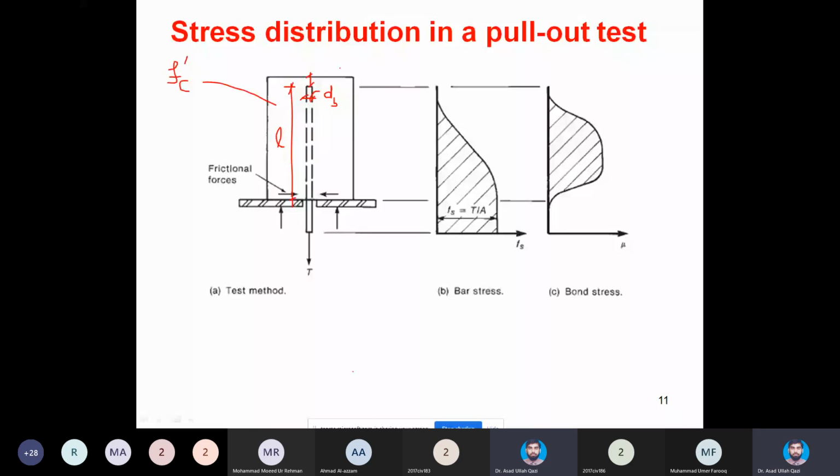You know the bar grade as well. You know this bar which is present in the concrete cylinder is of grade 420 or grade 300. So you have a complete idea about the grade as well as about the diameter. In addition, once you pour the concrete in this cylinder, simultaneously you will pour the companion cylinder or cube.